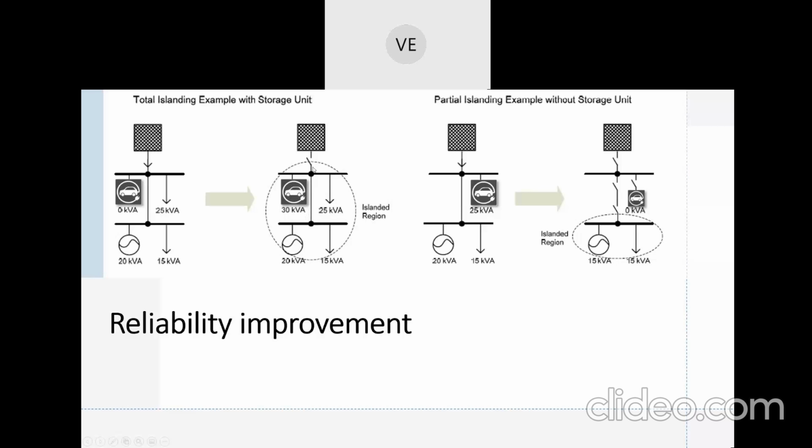So what should be done here is, before the islanding process itself, if they are planning an islanding activity, it should be communicated from the parking lot that up to 30 kVA support, 0 to 30 kVA, can be given from this particular parking lot. But again, there is the issue of availability of electric vehicles and uncertainty in state of charge because of the uncertainty in trips and travels of the electric vehicles.